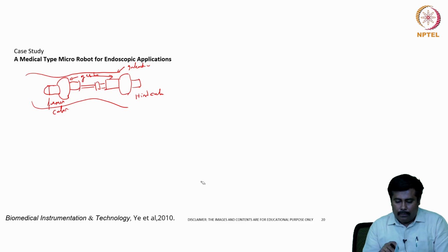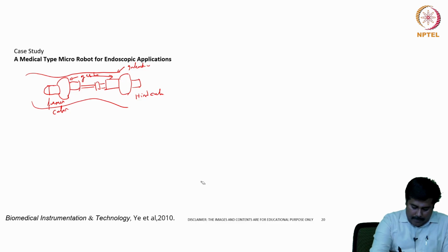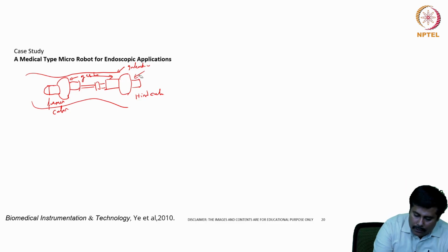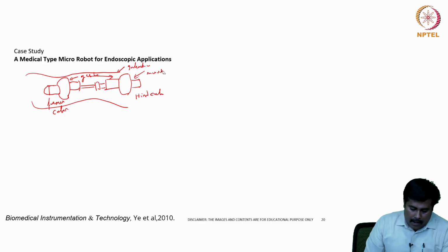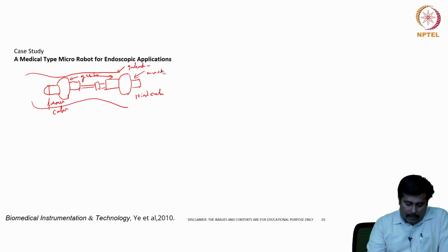In this locomotion, the fabricated micro pump will be assembled in the hind cabin of the micro robot. It will be kept over here, and the front and the back bag surrounding the outer surface of the micro robot will be inflated alternatively to engage the clamping function.